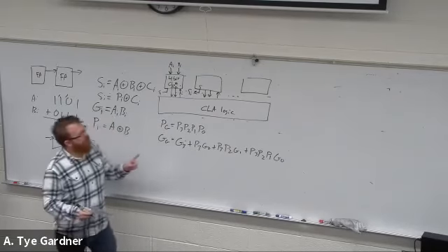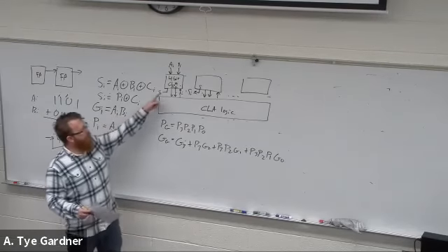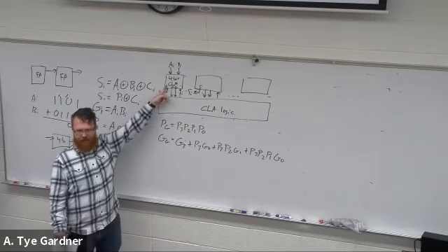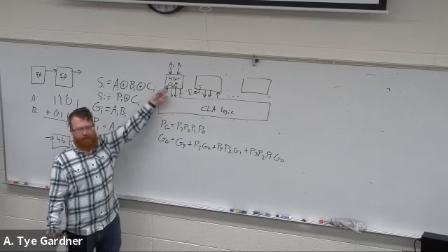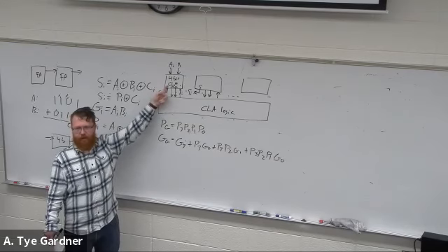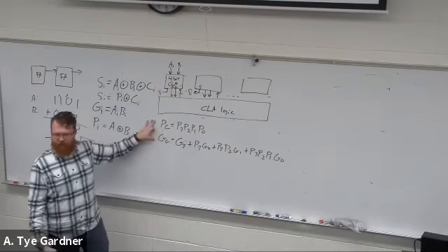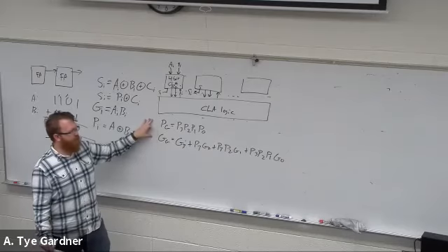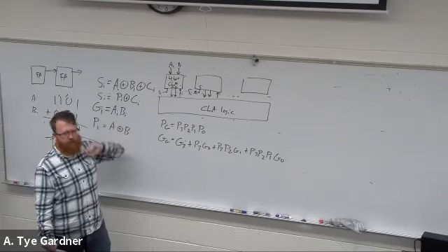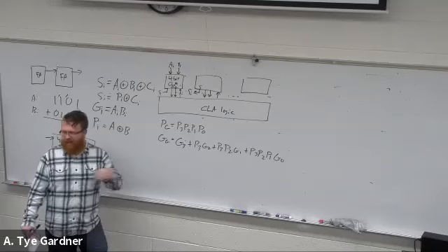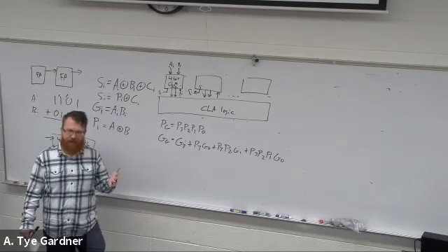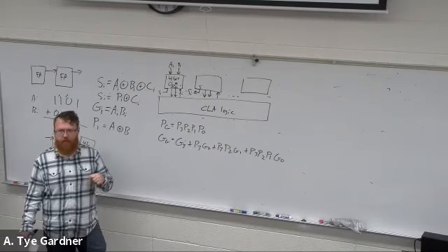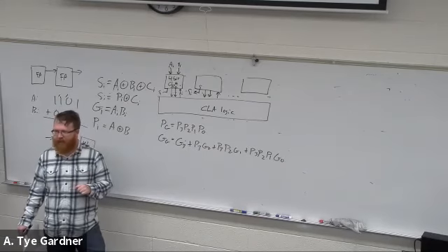So now I've decided that I'm okay with 4 propagation delays in each of my adders, and then I'll combine them into carry look ahead. I can adjust how big these bits are in order to adjust the level of complexity that the generate statements are versus the speed, right? It's not an analog tuner, right? There's very discrete steps, but I get to choose 1, 2, 3, 4, 5, 6, 7, 8 bits, however I want, in order to tinker with the speed of my carry look ahead.